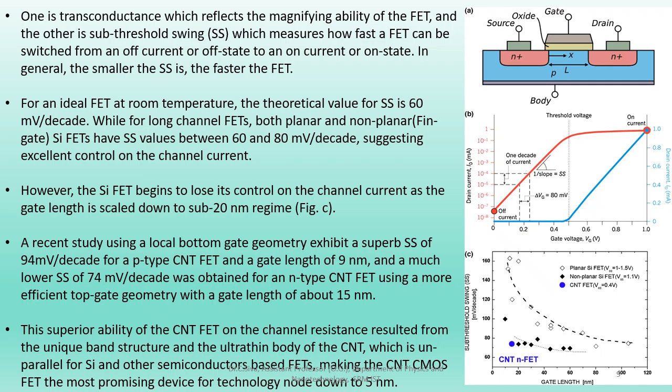Any reliable doping methodology is not viable for CNT. Doping would disrupt the sp2 lattice, reducing the mobility. As a result, early CNT FETs were Schottky barrier devices where the polarity was determined by the metal-CNT interface rather than dopant atoms. This limited performance and slowed CMOS development.